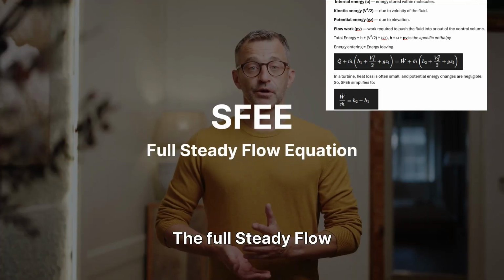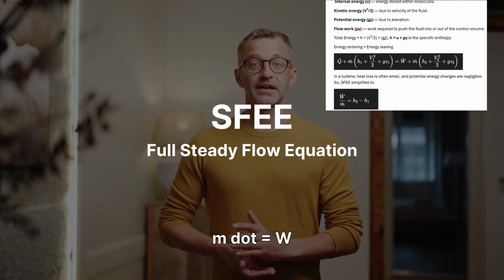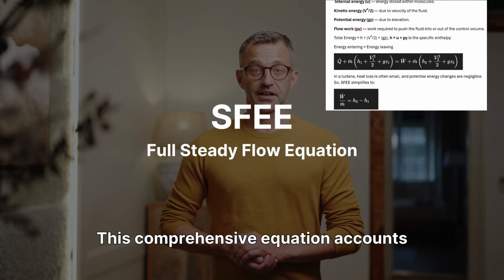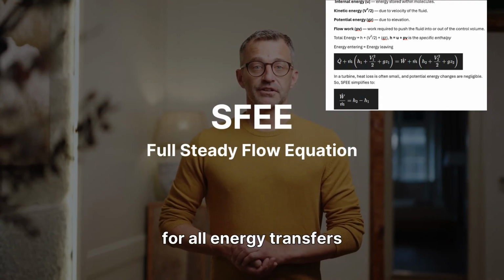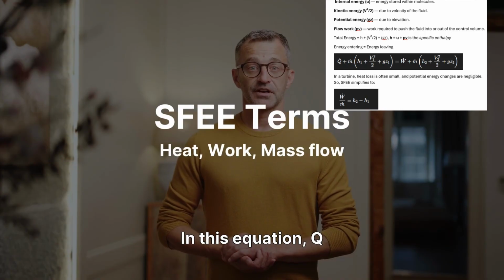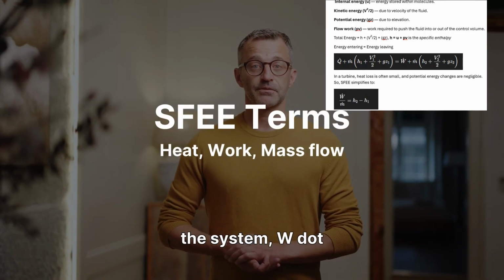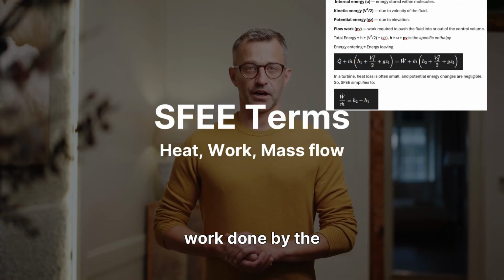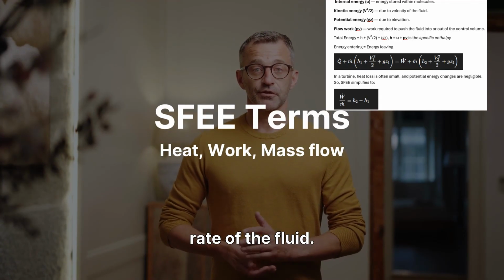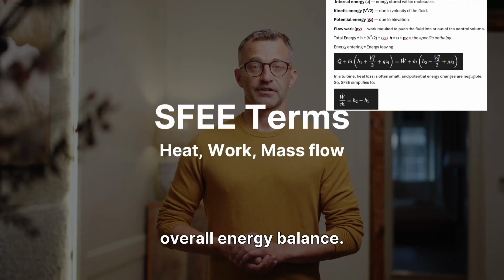The full steady flow energy equation is expressed as Q dot plus m dot times the inlet energy terms equals W dot plus m dot times the outlet energy terms. This comprehensive equation accounts for all energy transfers and transformations in a steady flow process. In this equation, Q dot signifies the rate of heat transfer to the system, W dot denotes the rate of work done by the system, and m dot represents the mass flow rate of the fluid. Each term plays a vital role in the overall energy balance.